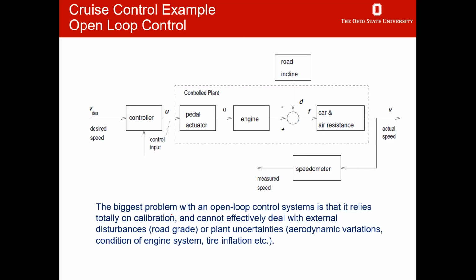Now, another example, this is also an example from MATLAB. This is one of their examples called the cruise control example. So most cars have cruise control nowadays, which is basic speed control, which means your model is the longitudinal dynamics of the car. At very best is some mx double dot equals a force type relation. But then there are other forces like drag forces due to aerodynamic resistance, slope forces because you might be going uphill, downhill, things that we call rolling resistance because there is friction, and tire forces. Okay, so neglecting all those for the time being,